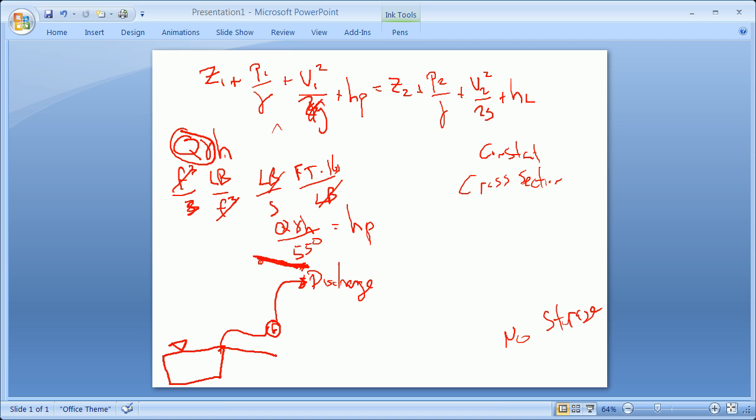It's down, and you have this concept that the pump has got to kind of suck water and then push water. And I want to now define two terms. The difference between the pump and the free water surface is the net positive suction head. And then we have, in fact, the total head, which is going to be equal to the head of the pump. It's going to be equal to the static head plus the dynamic head.